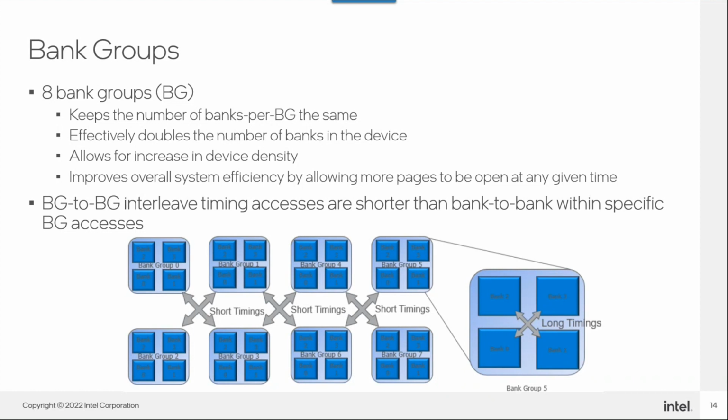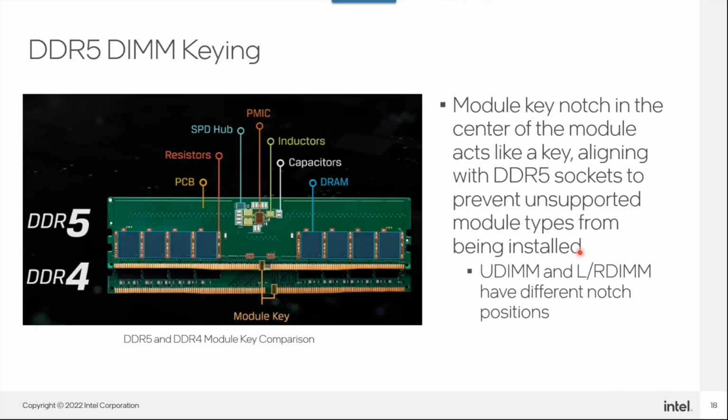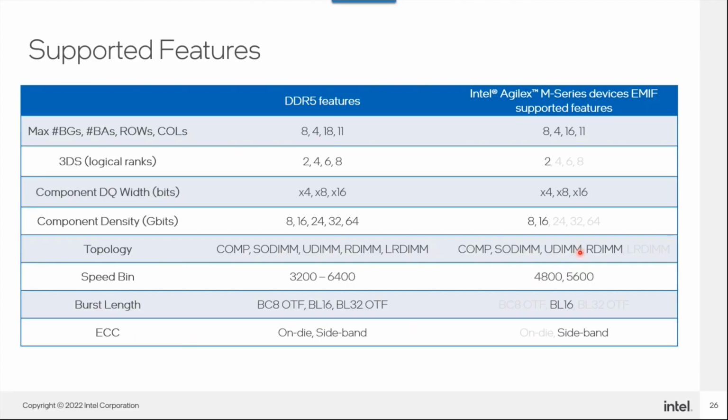So to give you a very specific answer, I need a little more detail, and you can reach out to Steven, and then Steven can help me reach out to you. In general, if you have 2 controllers on the same side of the Agilex, there are restrictions in terms of IO bank sharing. If you look at our Agilex F series and I series architecture, you will see there are 96 IO pins, and the IO bank is divided into 2 sub IO groups of 48. So there is no sharing allowed within that 48.